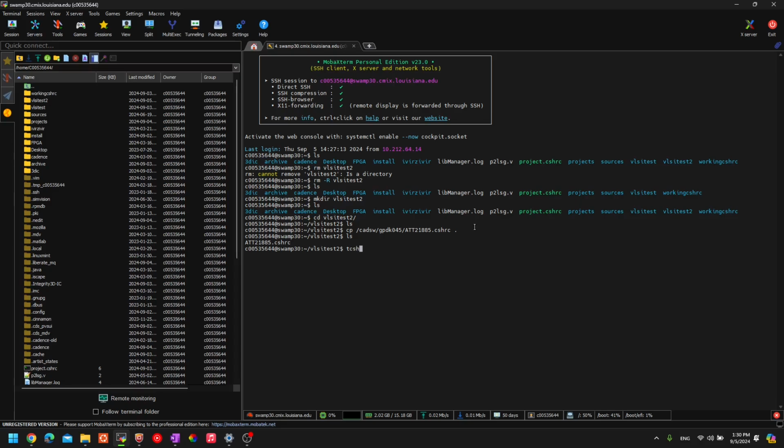type in tcsh in order to go into Turbo C Shell. Right. After you enter that, you'll have square brackets and your C number as well as directory in between those square brackets. So for now, you will source that .cshrc file. So source and then type in att tab and then do it. All right. Just in case, do it again. Okay, it already sourced the file.